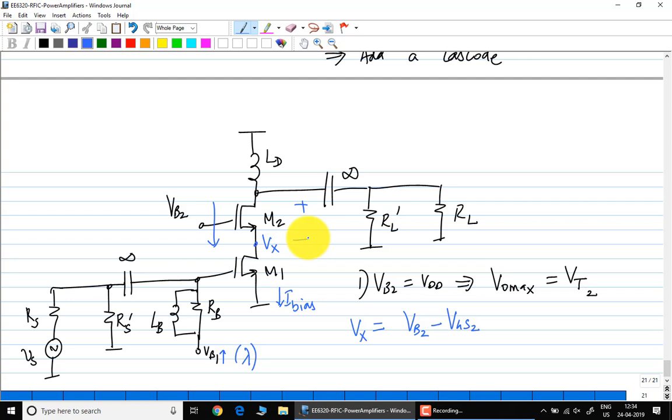And with these kinds of things you will see all kinds of second order effects. For example, you will suddenly see that for such a wide transistor, threshold voltage is changing as a function of the width of the transistor. It is possible. It was supposed to be 400, it's suddenly something different. Those kind of second order effects you should plan for, you should expect.